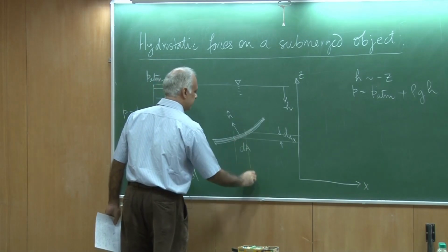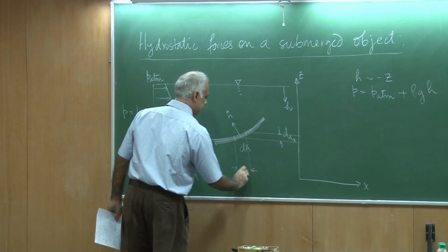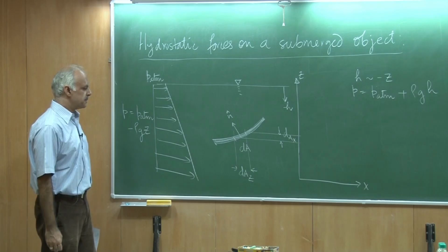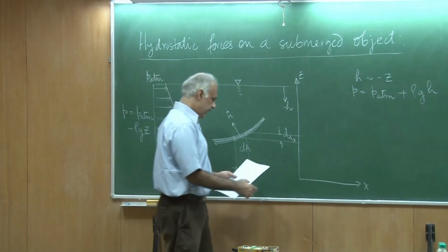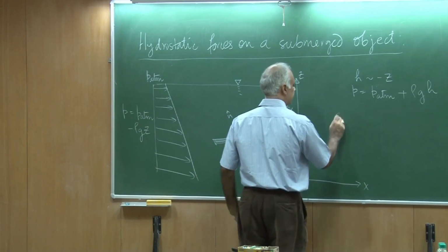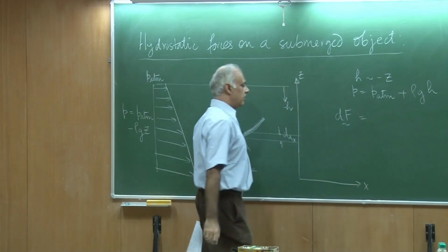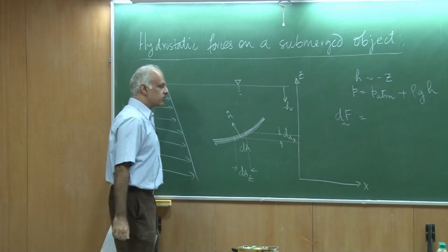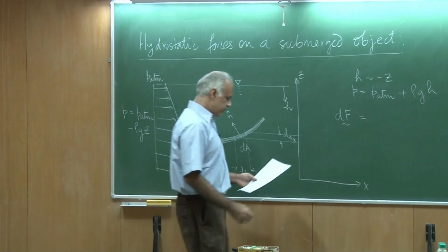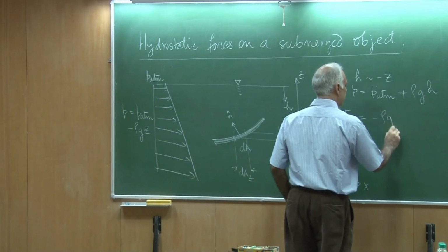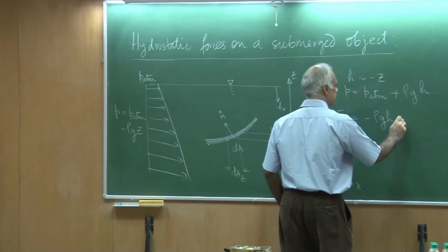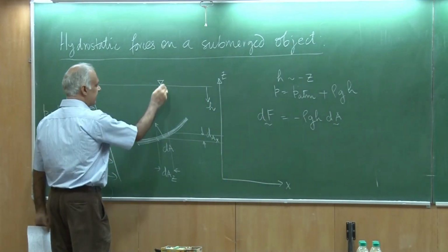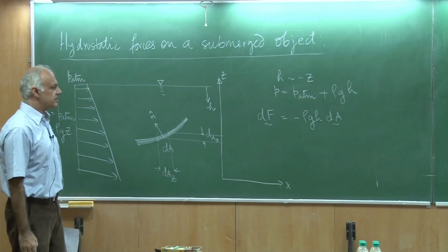Similarly, this projection, I am going to call dAz. Okay. And now I could talk about the dF, which is the force acting on this little element here because of the fluid static pressure, and that we know is going to be minus rho g h times dA, where this height is h, as I have shown in the diagram.